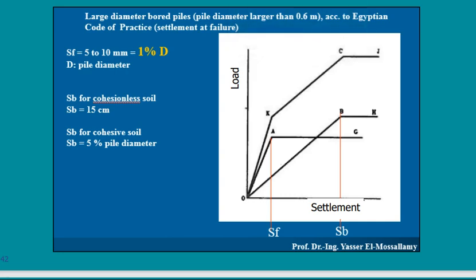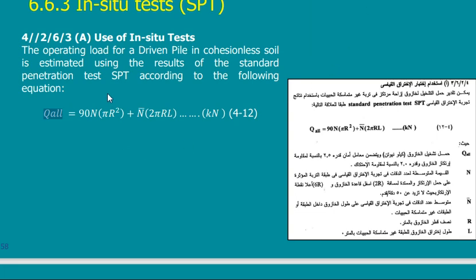The second method, which is the drawing, we are drawing a curve till reaching failure, so it also deals with the ultimate. In this method, the equation gives you directly the allowable. So please remember this, it's very important, because you don't get a number and divide it by the factor of safety, because it is already divided by the factor of safety.